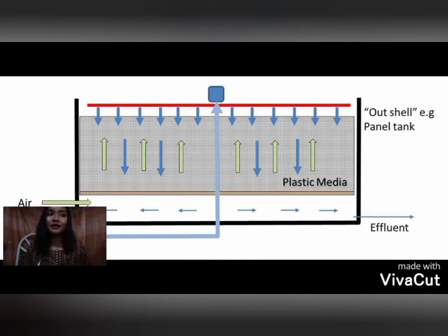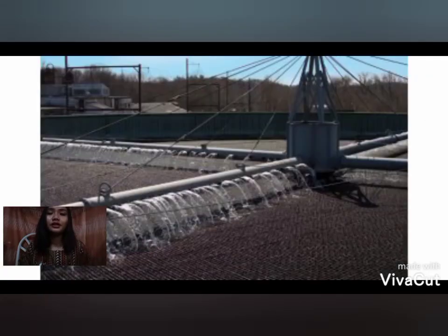But these trickling filters have certain limitations. Limitations like under organic loadings, slime growths plug the void spaces between rocks, causing flooding and failure of the system.